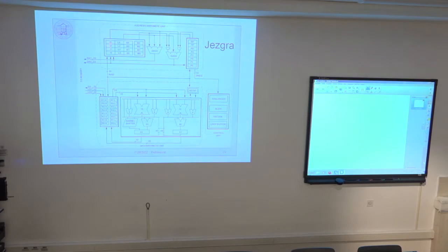And also what is new here, it has this base pointer. As I described previously, with this simple architecture, the base address of the buffer had to be on an integer multiple of the first power of 2 greater than the modulus. So for example, if the modulus was 17, then the first larger power of 2 would be 32, and this first address of the buffer must be divisible by 32.